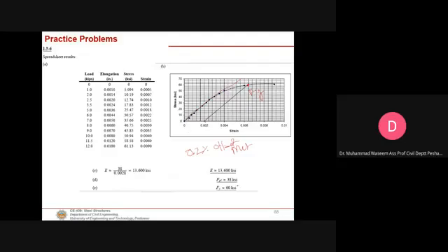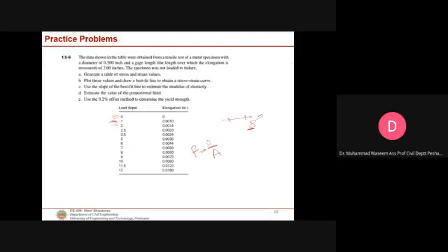It requires you to calculate this Fy. It requires you to calculate this proportional limit. So this is the proportional limit, like the tangent, and they are coinciding with this portion of the stress-strain curve. So this value will be your proportional stress. Okay. So obviously I want you to go through these examples.